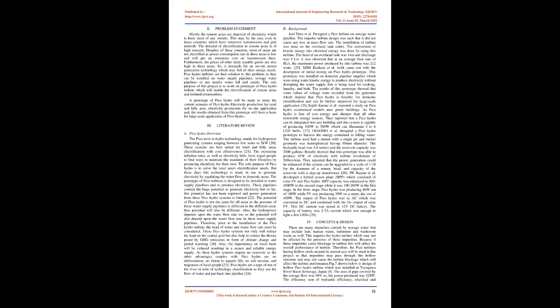Fig. 4 Pelton wheel for small hydro projects. Cross-flow turbines. These turbines were designed by Ossberger Co., that is why they are called Ossberger turbines. These turbines are drum-shaped, having cylindrical-shaped runners. The cylindrical-shaped runner is equipped with curved vanes against which the rectangular section nozzles are directed.